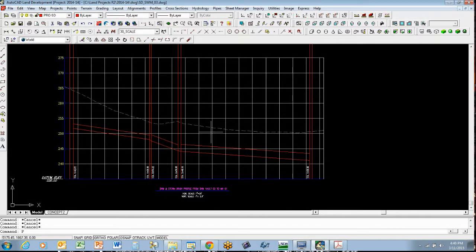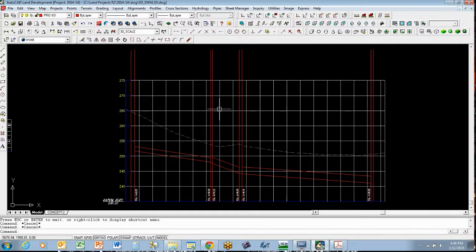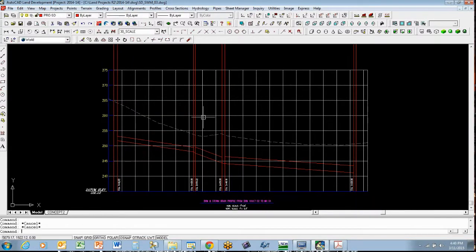So at manhole, this is manhole 1, manhole 2, yard inlet number 6, and then this is back over to the stormwater management vault. So what we're going to do is start with yard inlet number 6, and let's see what the top of that structure is.